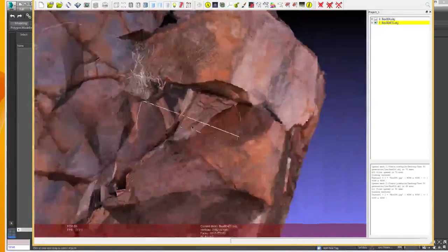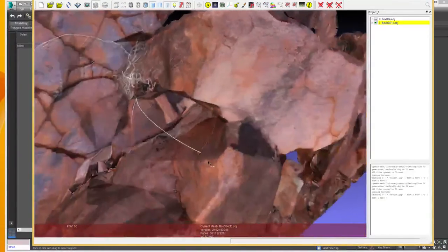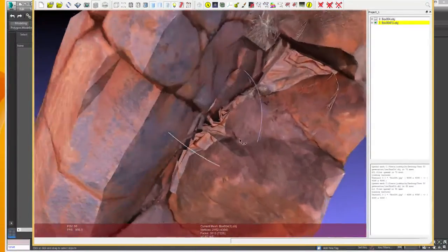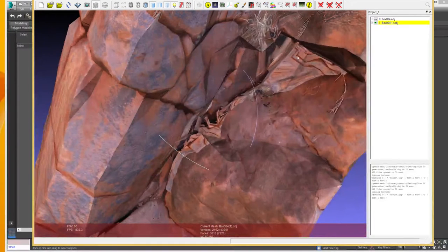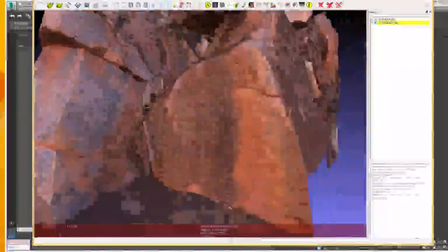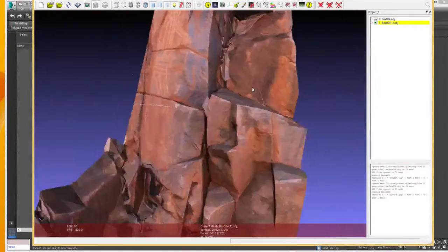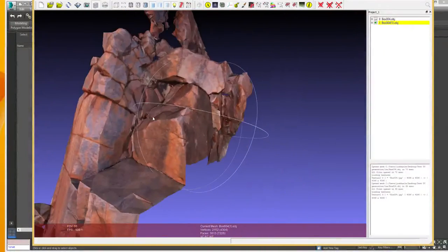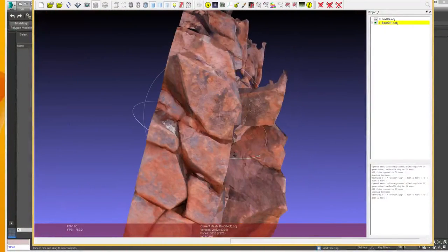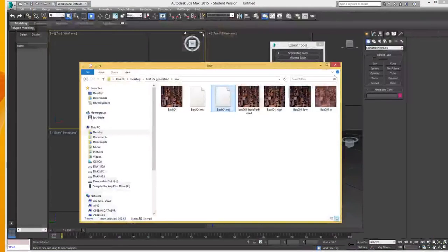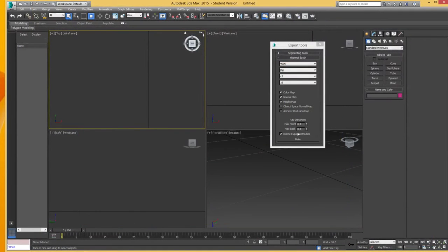So you get these weird artifacts. They're very, very easy to identify once you know what to look for, very strange things where basically that line there is being projected onto that section there. So if you start getting those sort of artifacts in the corners of your model, then you know that your ray casting distance is too long. As I say though, this value is pretty sane, it's quite a good one. So there should be no reason, unless you start seeing weird effects, to change it.